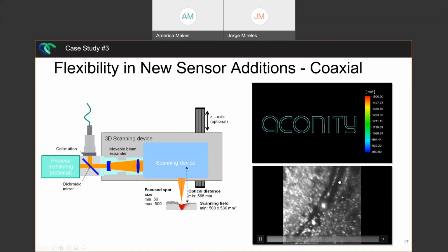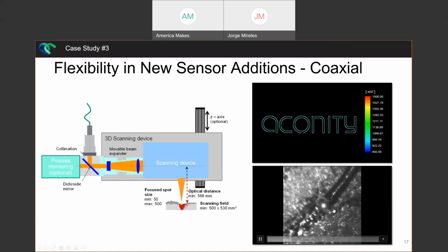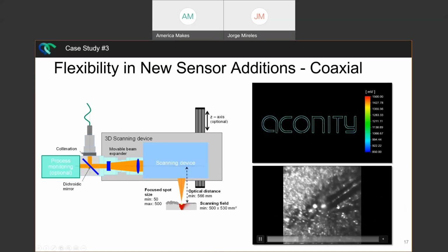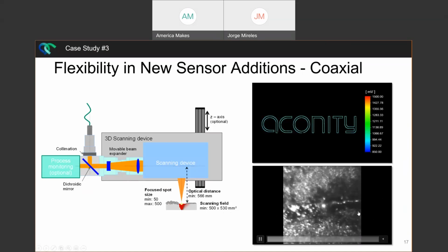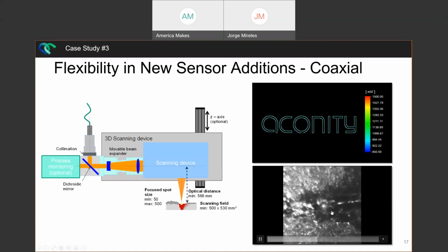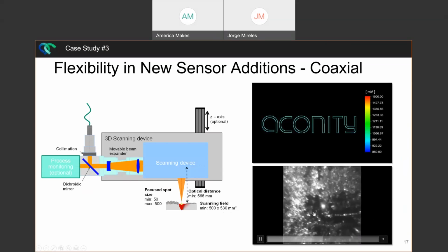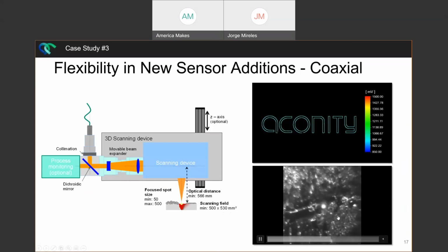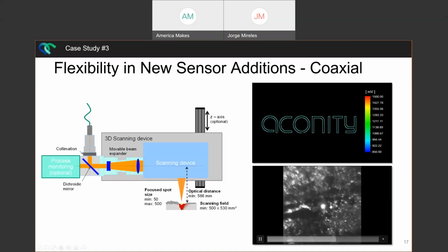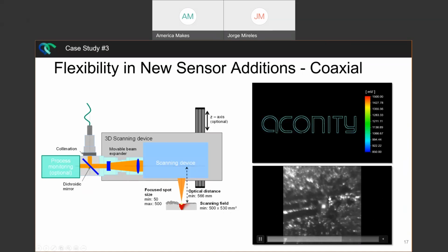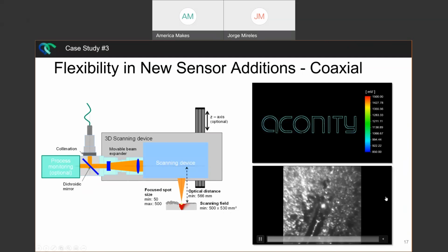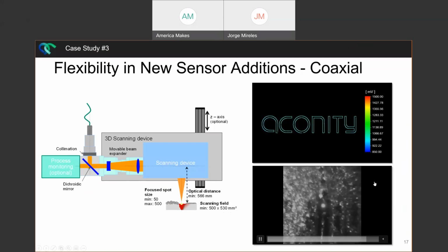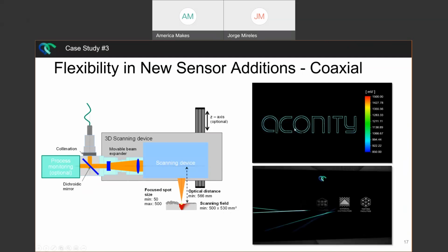And so with high-speed camera, you're obviously able to get some really nice depictions of your melt pool. You're able to really gain a good understanding of your powder dynamics. So here you see powder being sucked into this melt pool, which is really interesting, or just the jumping around of powder particles, and it really has been used a lot to validate models and gain a better understanding of the process.